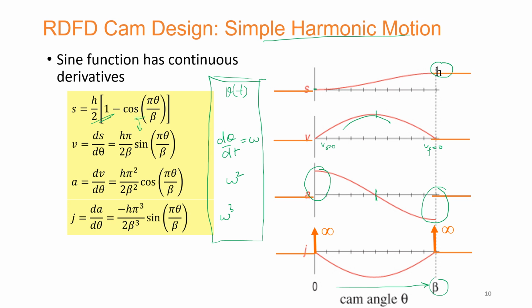Because we have said that this is only part of the cam profile. This is only the rise function that we are exhibiting, but actually in a cam profile, for the one that we are trying over here, which is RF DF, you're going to have the other motion segments as well. So when you have those motion segments as well, you're going to have this area to be clearly a problematic area, and this discontinuity to be problematic as well. And this further is exhibited when you plot the jerk term, and you can find the infinite impulses over here, which actually is not at all desired.